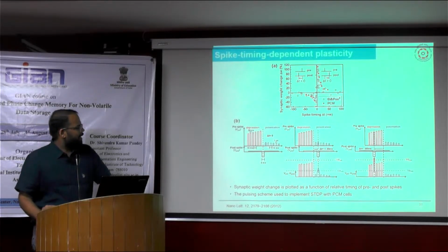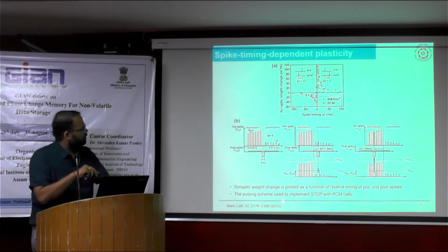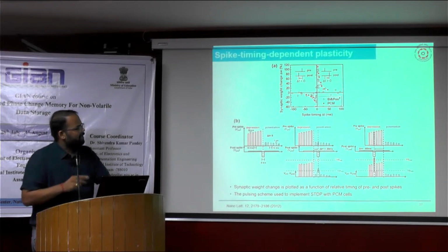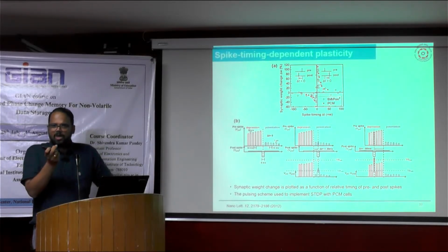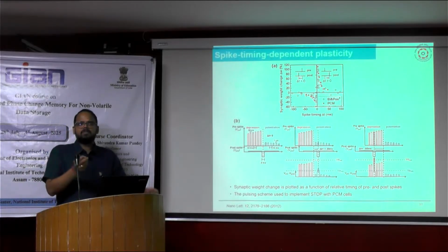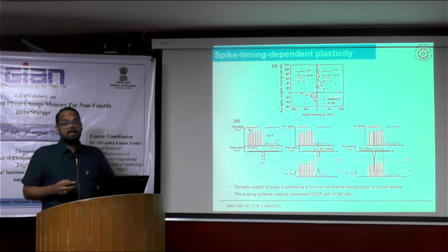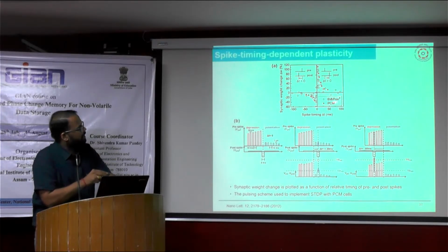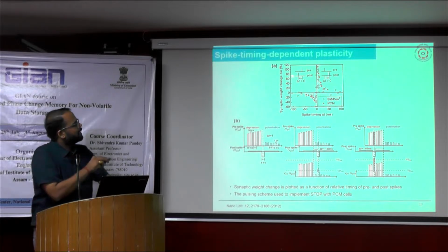So what happens here, reported in this particular work, they have tested time dependent weight change. It means for what time you are providing the electrical pulses based on the time duration, and then they tested the change in synaptic weight, and then they were correlating with the biological method reported by Bi and Poo, and they were trying to identify, yes, the PCM device almost mimics it. It's showing the same property of conductance change.